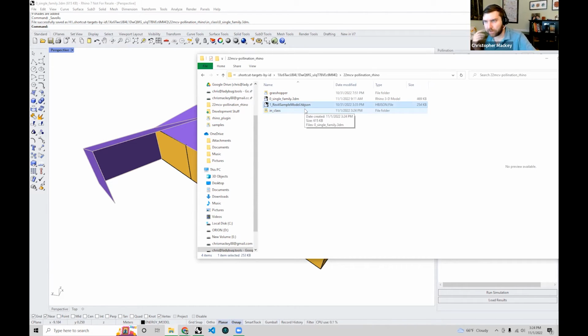The thing that we promise whenever you save things as an HPJSON or open up an HPJSON in our software is that all of the attributes that you assign to that model will come through that import and export process. We can't always guarantee, let's say if you import an IDF, that we're going to be able to bring everything from that IDF into our software. But from an HPJSON, you will always get everything coming through.